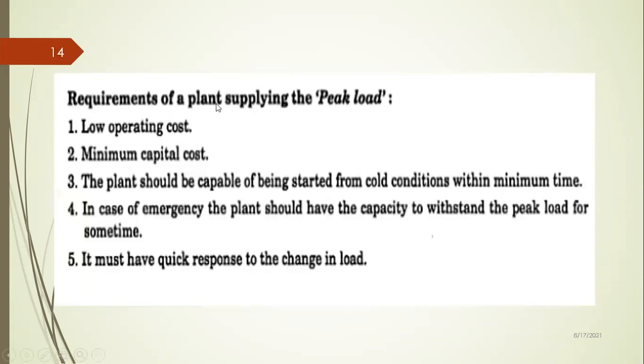Now the requirements for the plant supplying the peak load. For the peak load, low operating cost and minimum capital cost must be there. The plant should be capable of being started from cold condition within a minimum time. So this is the main requirement, this number 3, for the peak load power plants, that the plant should be capable of being started from the cold conditions within a minimum time.